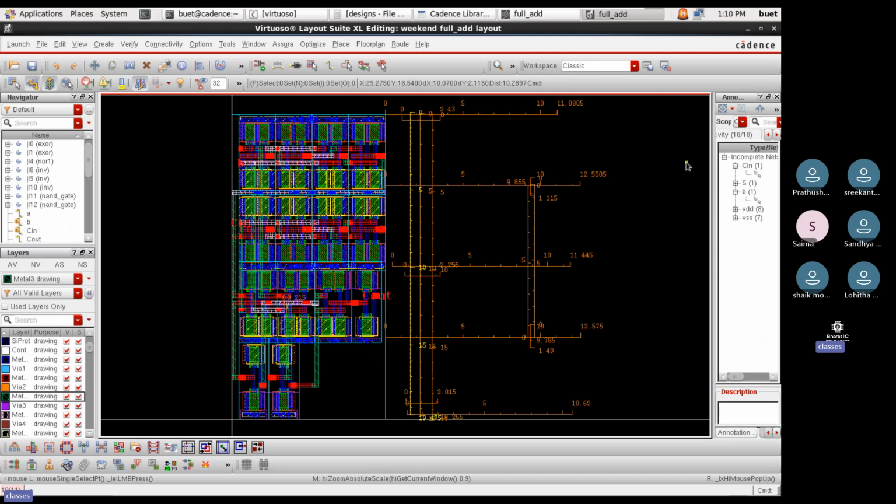I have done this to show you guys how to do the VDD and VSS power planning. So I am not doing this one now. It will take some more half an hour to do it actually, because some DRC issues will come up when connecting them. So this is how you can route a full adder. This is what the floor plan routing of a full adder looks like. You can modify the device placement also, and you can do it accordingly.